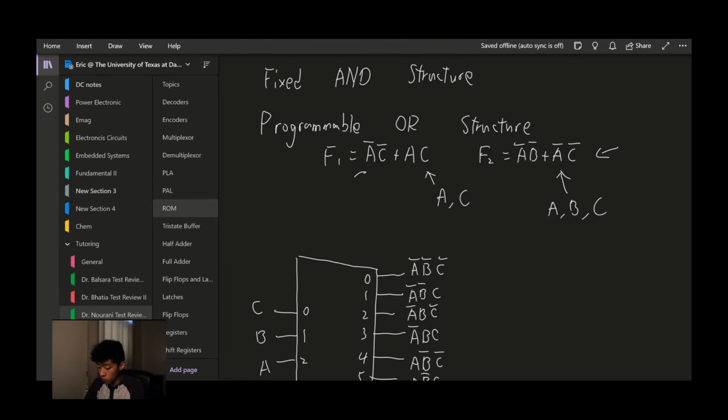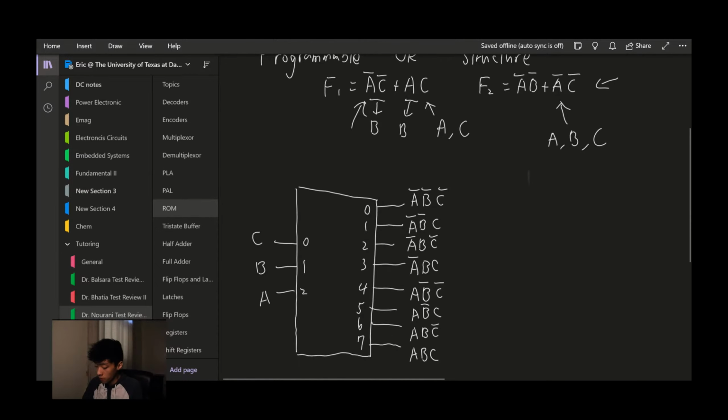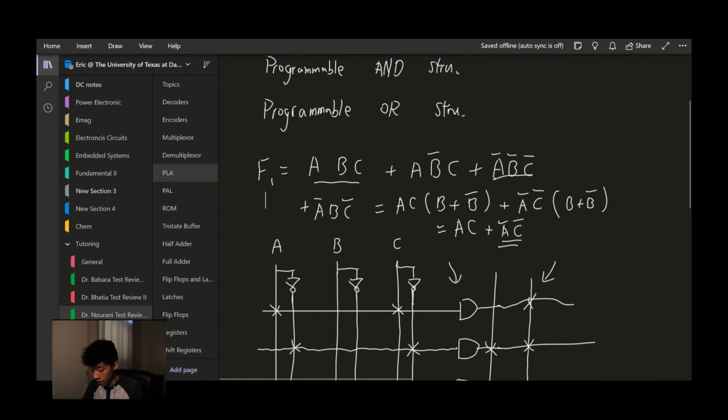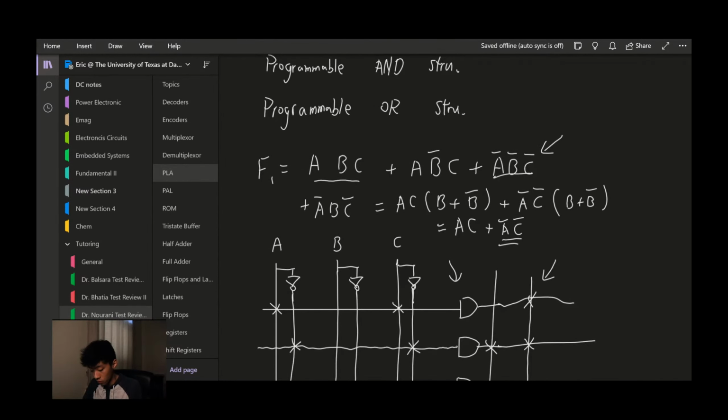And now going back to this term, we see that this term doesn't contain AB. So we will have to do a Shannon expansion for that. For this term as well, we have to do Shannon expansion to get B into each term. But previously, if we use the unsimplified version of F1 here, we can already have all the variables in each term.